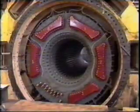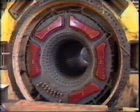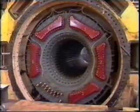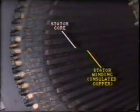The electricity is actually produced in the stator winding. This is the stationary winding which is supported by the stator frame. The stator winding consists of insulated copper conductors which are embedded in the slots of the stator core. The slots run end to end.